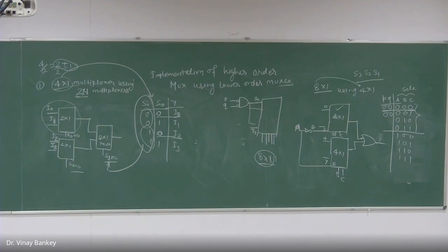Okay, now we saw the multiplexers. Now we'll jump on to the demultiplexers. There is another combinational circuit that comes into the picture, where it has only one input, and according to the selection lines, there are many outputs. Exactly contrary to the multiplexer, where we have 3 selection lines and 8 inputs, or 2 selection lines and 4 inputs. So in the demultiplexer, we have 1 input, selection lines, and 2 power of the selection lines as the outputs. Correct?